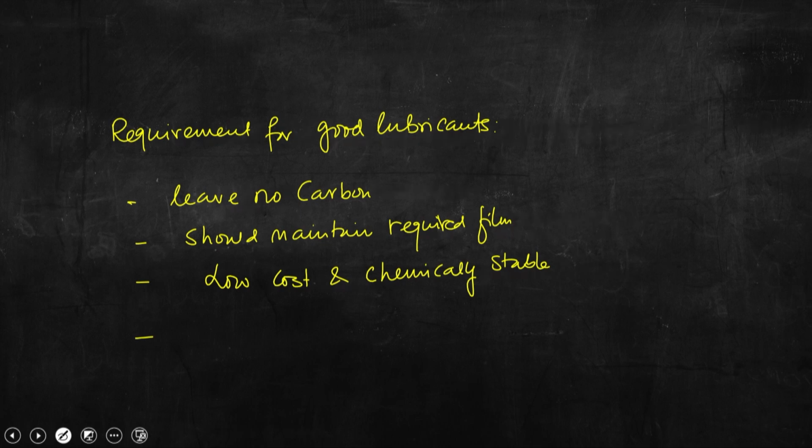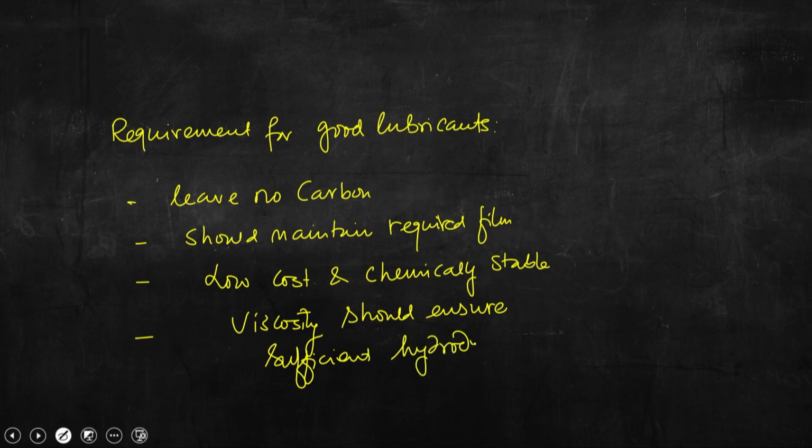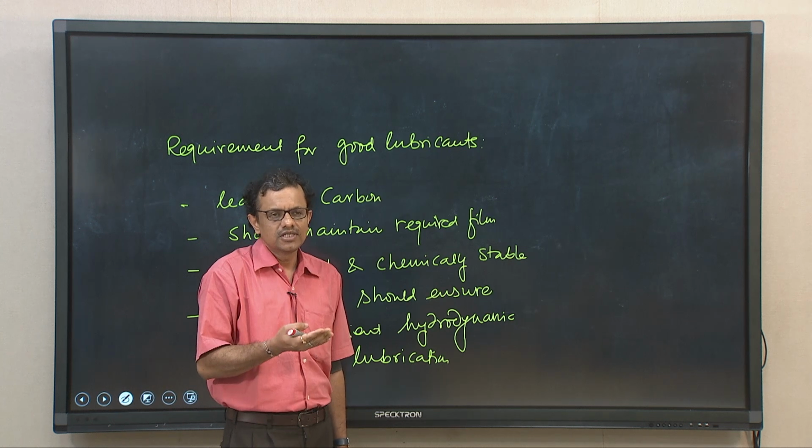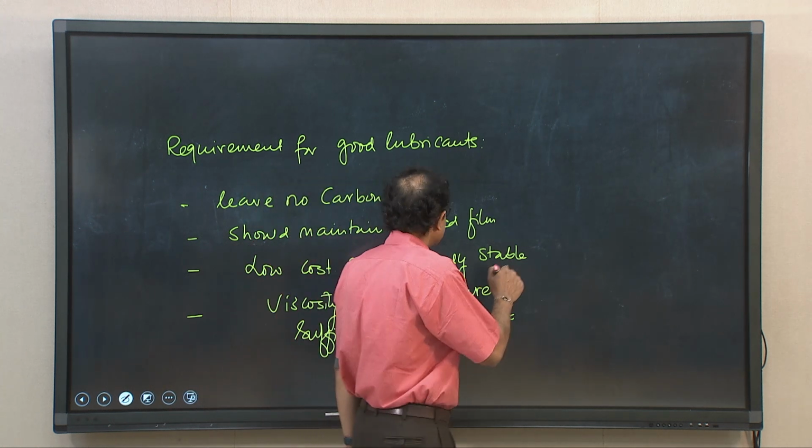And then viscosity should ensure sufficient hydrodynamic lubrication. It should be chemically stable, because the lubricant needs to face high temperature. So, it should not be unstable chemically, it should not decompose, it should not dissociate, all these things, and also it should be physically stable.